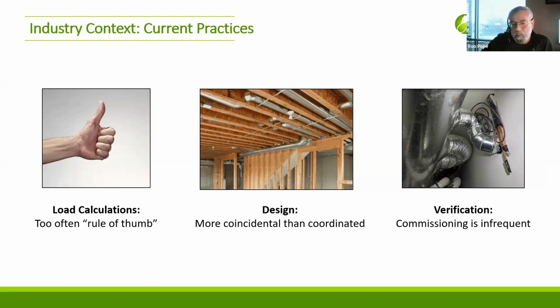Load calculations don't get done as required by code, which is a certain standard of measuring heat loss and heat gain that's verifiable. It's called F280. That's rarely used. It's changing, granted, right now, but still the majority of calculations are rule of thumb. And of course, that's not great. Design is more coincidental than coordinated.